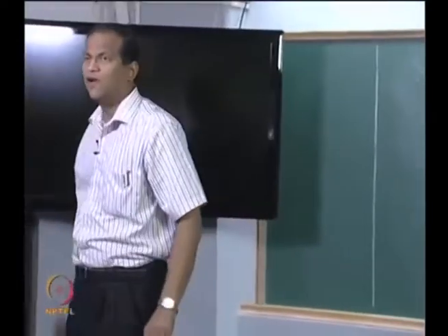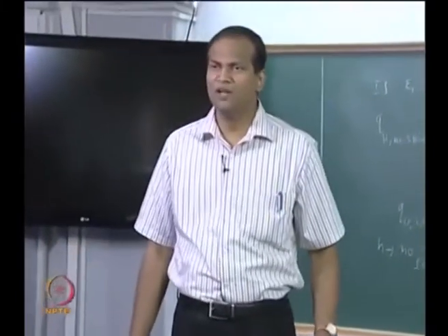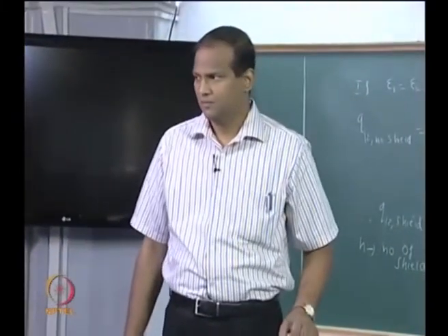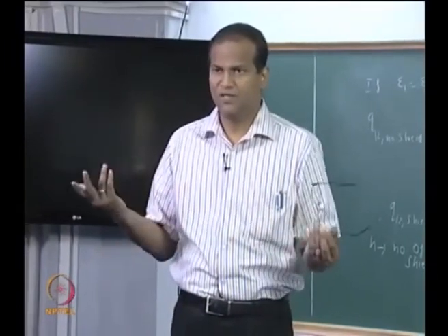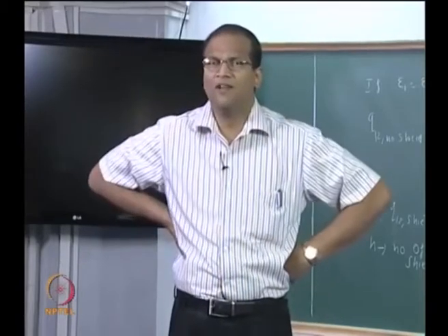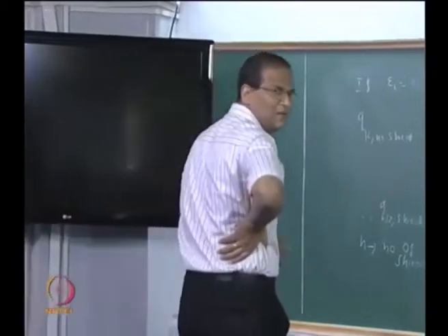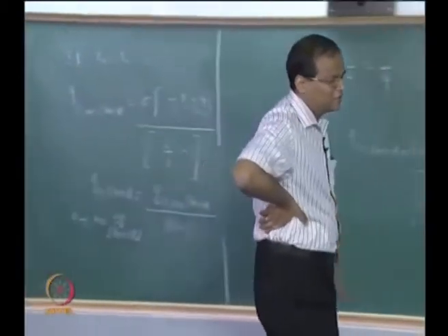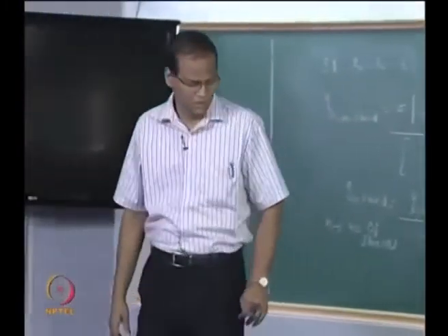So, just because you have vacuum, it does not mean that you have already insulated. If you have vacuum, you remove the convection, and there is no conduction because there is no medium, but radiation will be there. If you have evacuated and you also have n shields, you get what is called a radiation super insulation, okay. This is the concept of a super insulation, okay.